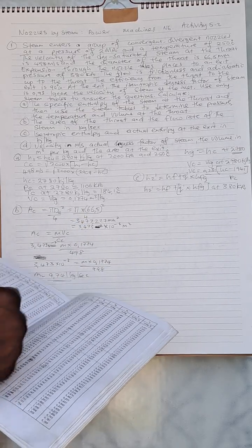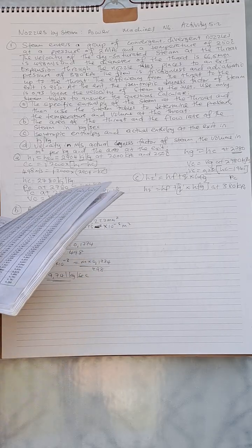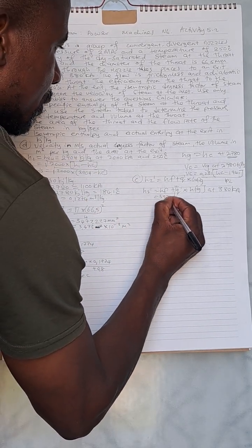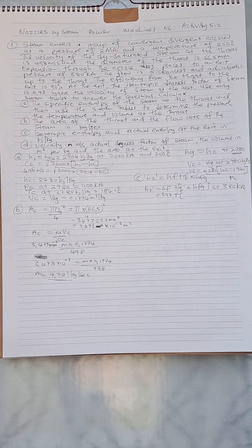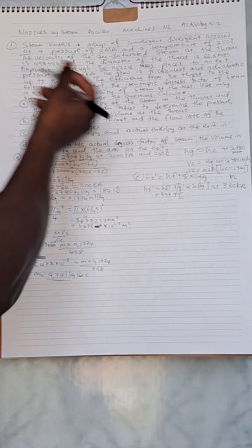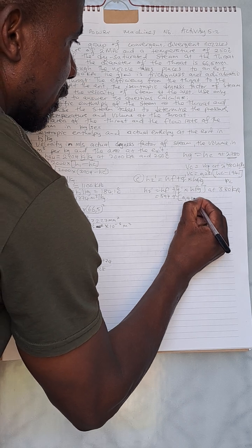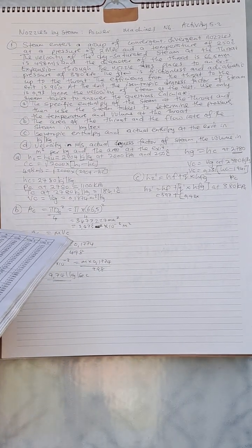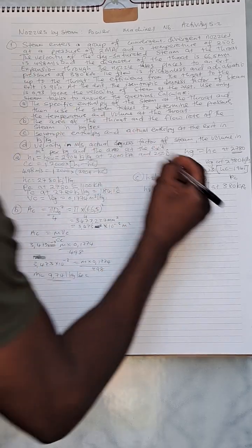Where is our 380? So our HF is 597, plus the isentropic dryness factor, which was given as 0.93, times our HFG. HFG at 380 is 2139.